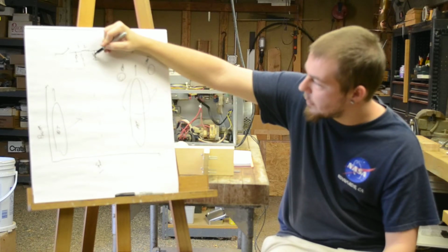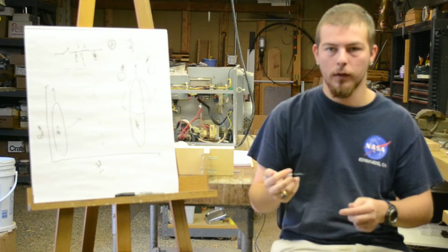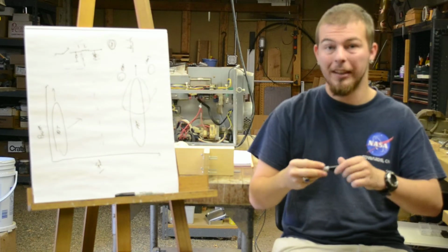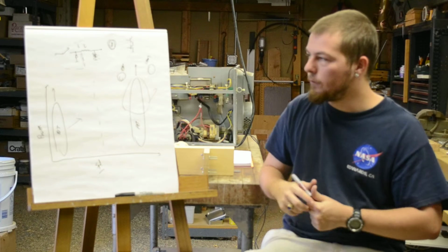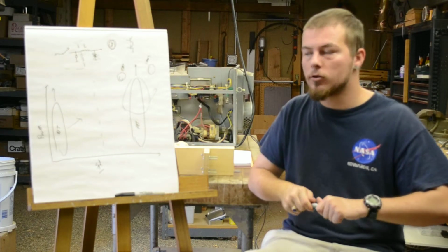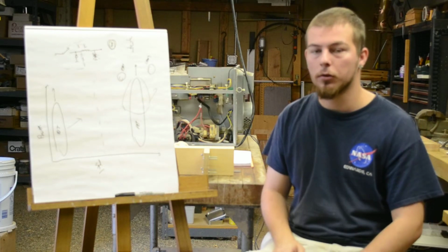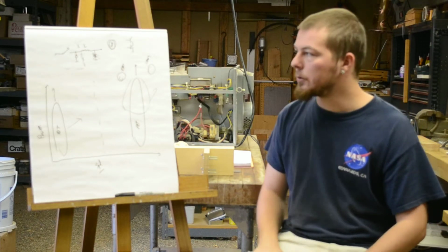Now, for the most part, we're going to act like this smoothing capacitor doesn't exist, because you're still going to produce the output without it. It doesn't directly affect the output. It affects the voltage ripple and the frequency component of the output. So it essentially just gives you a cleaner signal, but it doesn't actually impart anything to the circuit that you otherwise wouldn't be able to get.